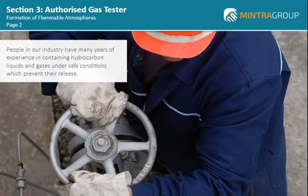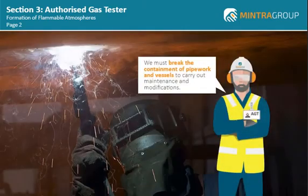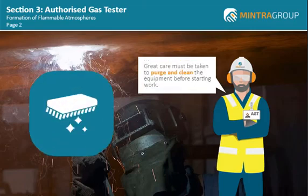People in our industry have many years of experience in containing hydrocarbon liquids and gases under safe conditions which prevent their release. Therefore, encountering flammable atmospheres is usually a rare occasion. However, at times we must break the containment of pipework and vessels to carry out maintenance and modifications. At these times, great care must be taken to purge and clean the equipment before starting work.